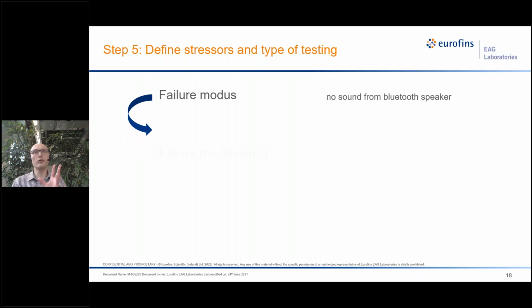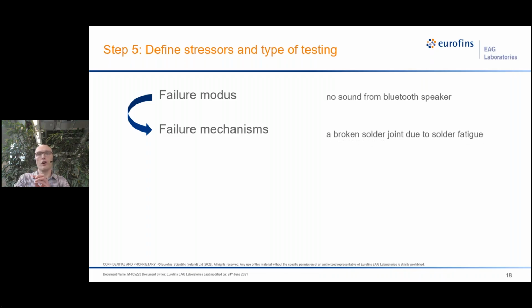Because we have researched the failure mechanisms using material analysis techniques within the Eurofins lab, we have been able to find out that the failure behavior is caused by a broken solder joint. A broken solder joint due to solder fatigue. Now that we know this, we can look at the different stressors that cause this failure behavior.